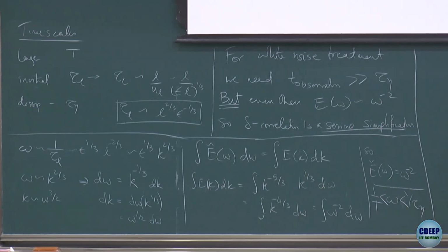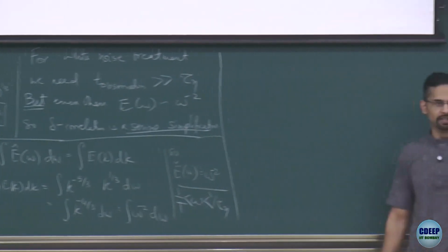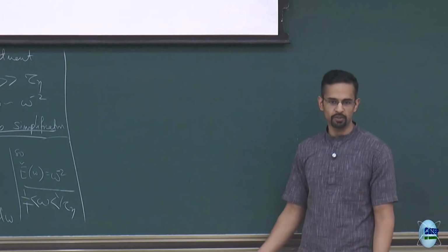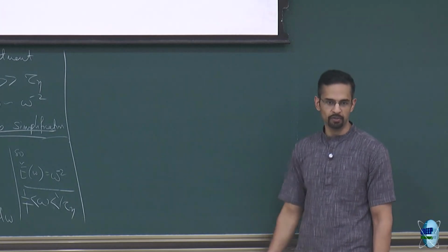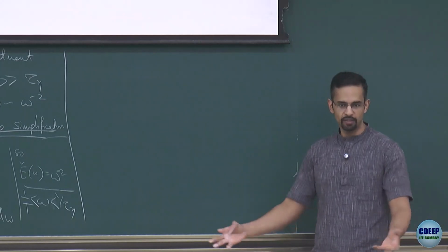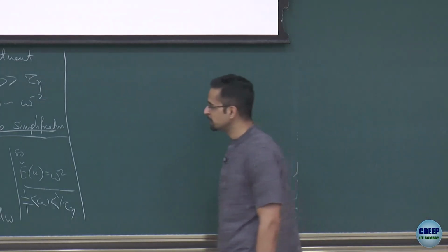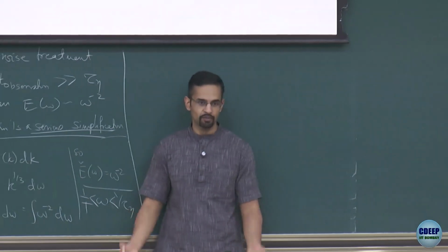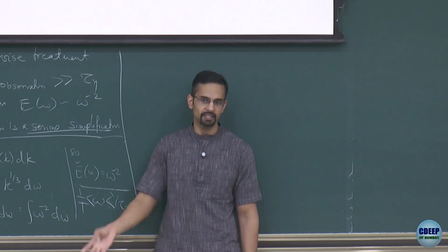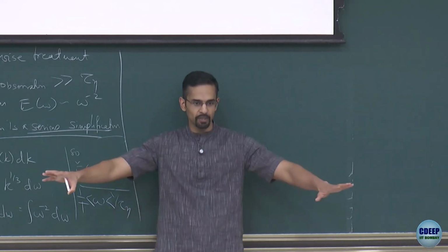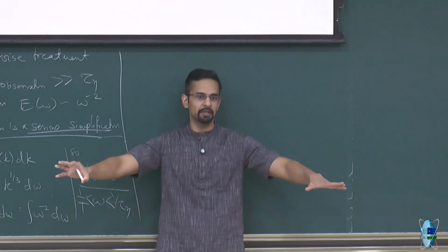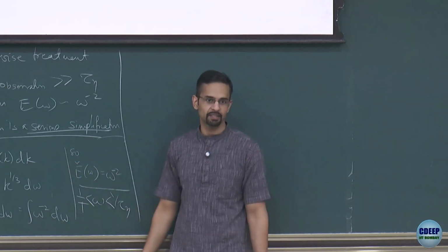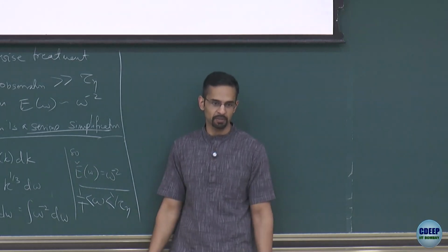So in space, we are able to build in the full spectral structure by taking Fourier modes with a nice power law distribution of amplitudes. We can take the Kolmogorov spectra in space and then do our stochastic modeling. But typically, if we want to get some kind of analytical results, we have to assume that the stochastic function is delta correlated in time. So I take some turbulent field, and the next time instant it's replaced by some completely other decorrelated field. This is a very serious, big approximation.